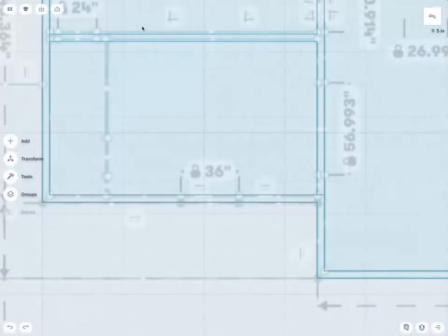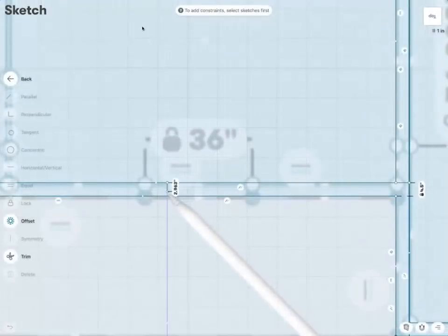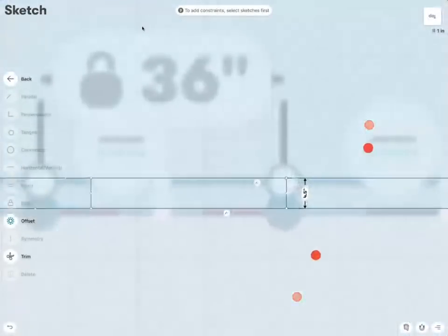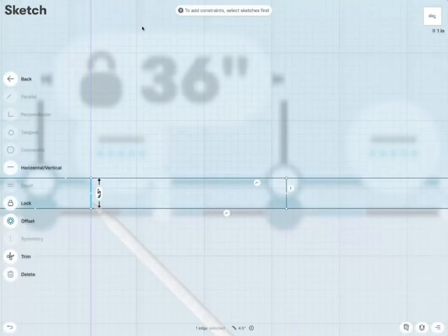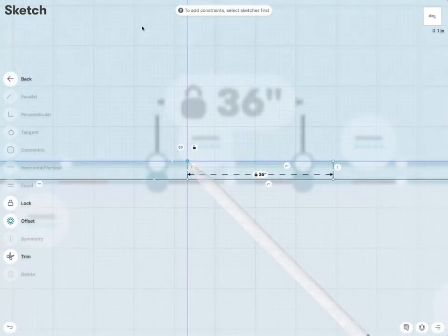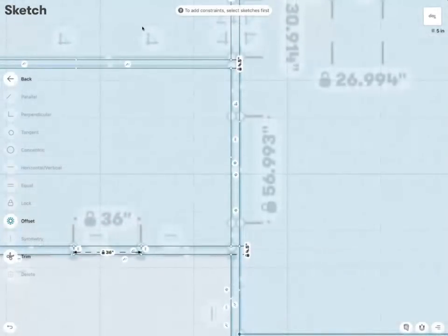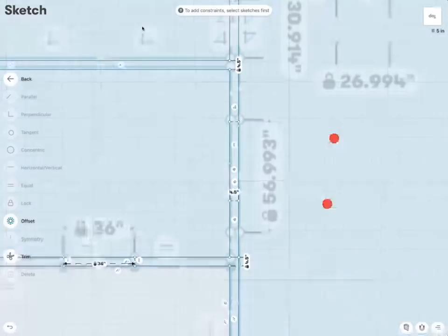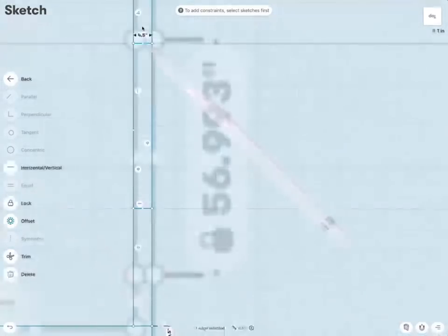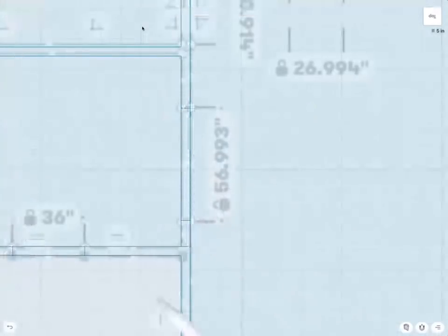The doors we also put into the floor plan. So for example, here, there is one door. There it's snapped to midpoint, so we have to be careful about it. Again, this can be vertical and vertical. The door, as we can see based on the image behind it, should be 36 inches. And I just moved this right there, so it somewhat lines up with what I have inside the design before. I can do another door here too. So horizontal and horizontal, and 56. And I select one point and drag it to where I need it.